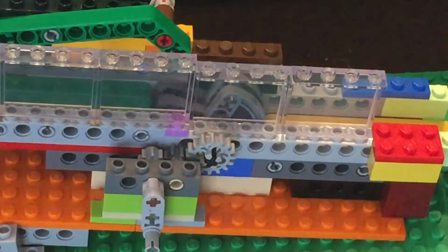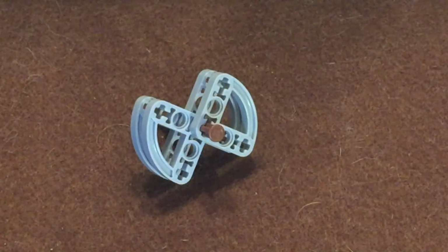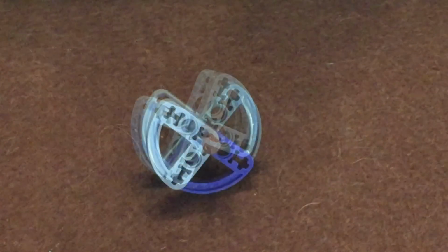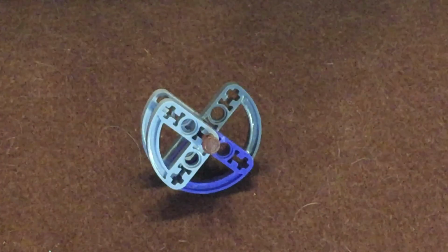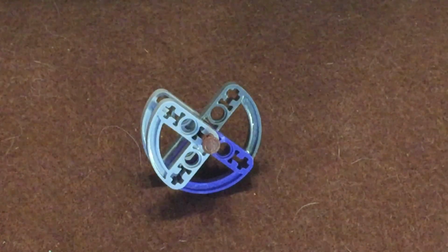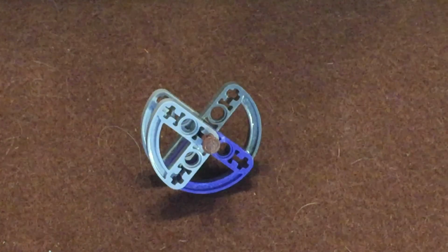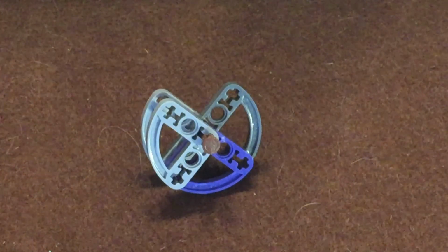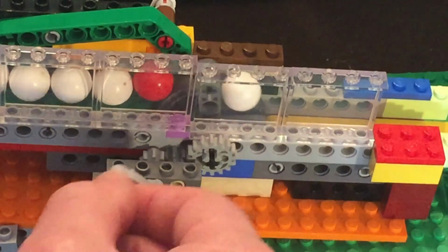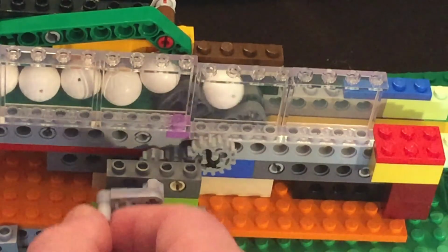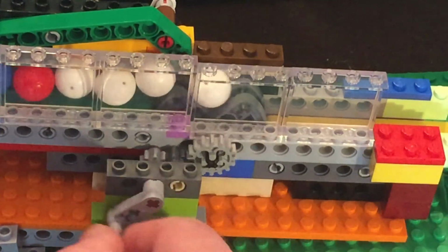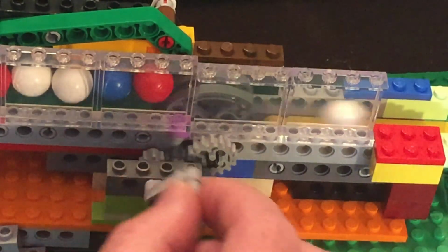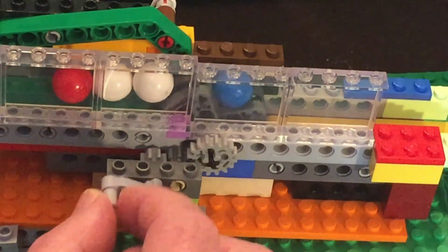There are two ways of implementing the wheel. There's the butterfly style, which will advance two balls per revolution, or you can use this design, which only has a single notch and only advances one ball per revolution. Which design to use really depends on the speed of the input power and what you're trying to do with it, but it's nice to have the flexibility. In this case, I'm using the butterfly wheel, but there's a 2-to-1 gear reduction between the input and the wheel, so I'm only advancing one ball per complete turn of the hand crank.